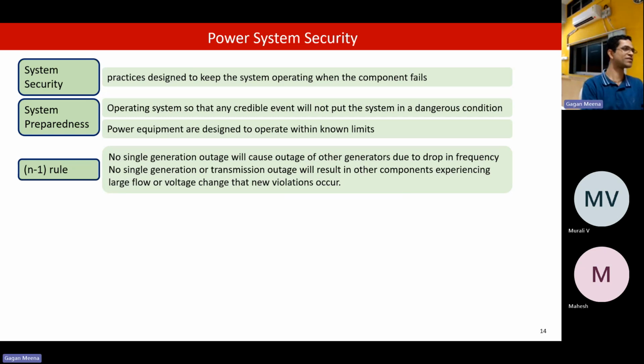The older the transmission system is, the more its capability to withstand these overloading situations for a longer duration reduces. We also need to know the actual thermal rating now of the transmission lines.